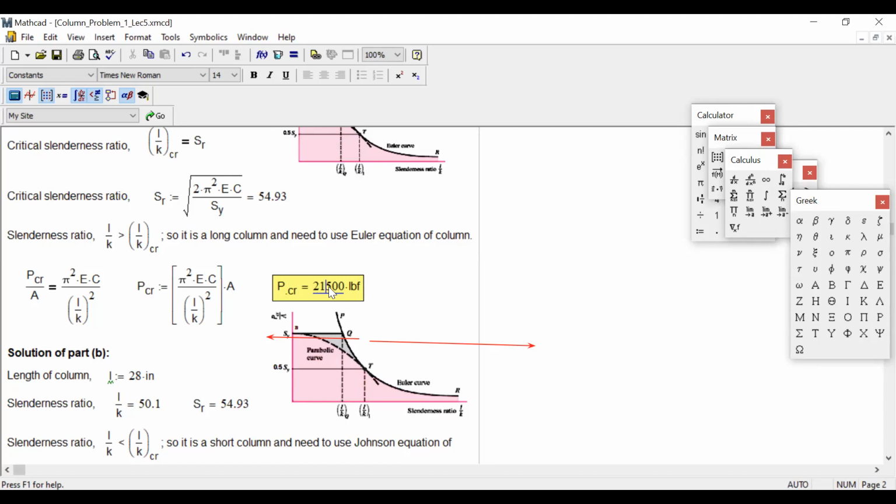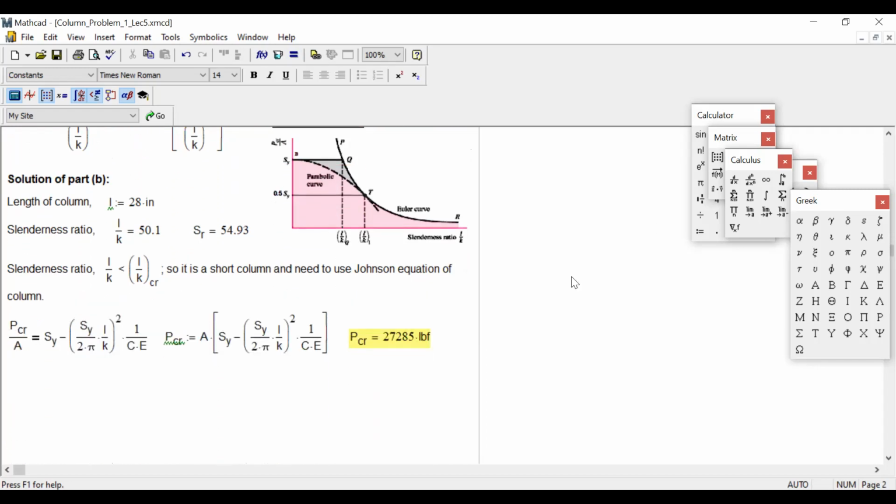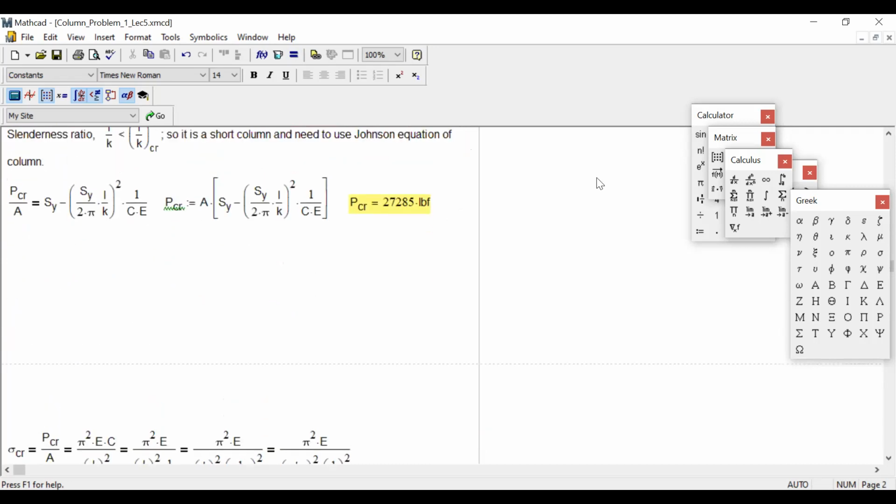Okay, but say you designed a column with 34 inch, but they found the length is 38 inch. So obviously you cannot install that one, right? Because the space is shorter. Then what needs to be done? You need to redesign, you need to analyze this again, because the length is increased, so the load carrying capacity will be reduced. Okay, so this is an example of how in real work you can apply your knowledge of solid mechanics, or knowledge of columns. Any question so far?